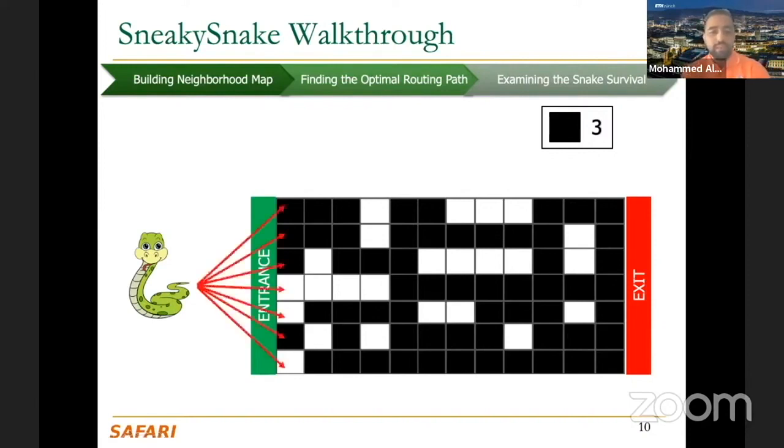So how do we solve it? It's very similar to the single net routing problem. In each row, you detect how many steps you can go further. So you find here 0 steps because you start with an obstacle or a module, then you cannot pass. Here you can move 4 steps forward, because your goal is always to go from left to the right. So you want to go as far as possible in each row. That is a greedy choice to get the shortest path.